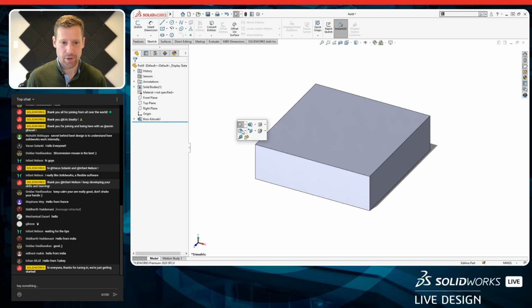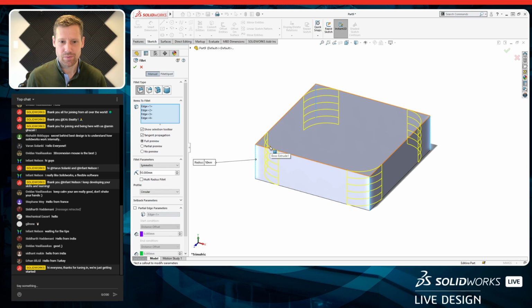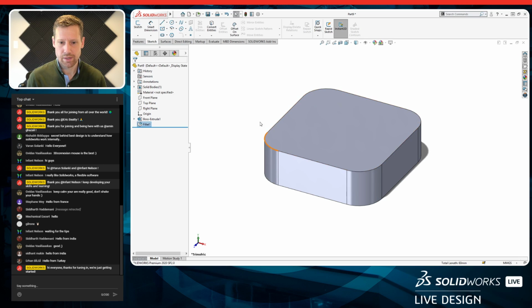I'm going to grab my S key here for my fillet tool. I'll select this vertical edge. I'm going to use this convenient pop-up here to select the other vertical edges as well. There's another one here, but I don't want all those edges. I just want the vertical ones. And that looks pretty good to me. We'll use the D key here and say OK. So now I have the start of my part. The corners and stuff need to be rounded off a little bit, but we'll get right into the first method